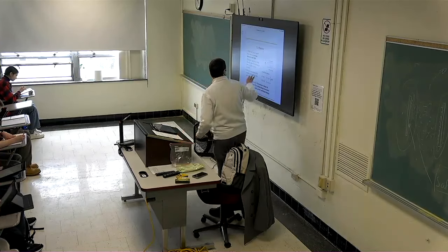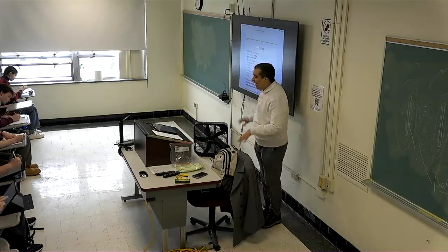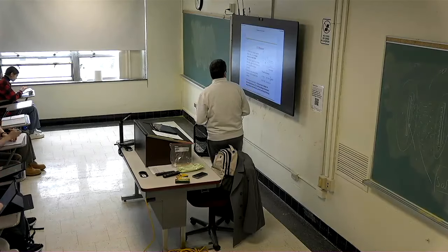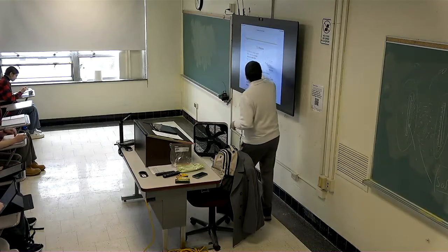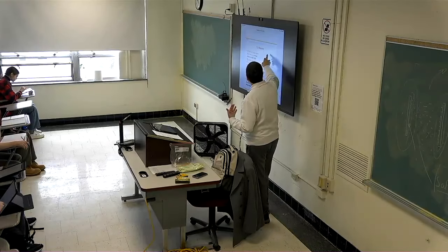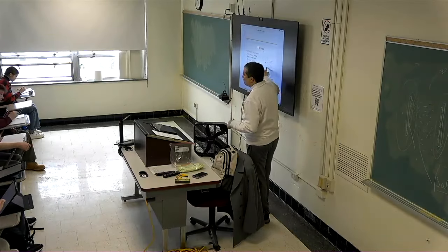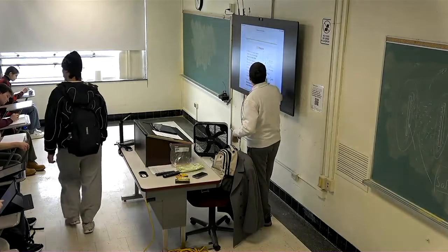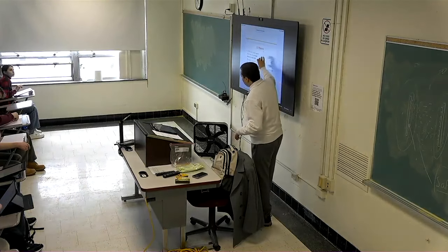Last session I plotted this triangle for you on the board, and I showed you that the pressure distribution inside this triangle is like this. Axial pressure is equal to this normal pressure over the inclined surface, and P at the bottom section, which is section Z, is equal to Pn plus 1/2 rho g delta Z.